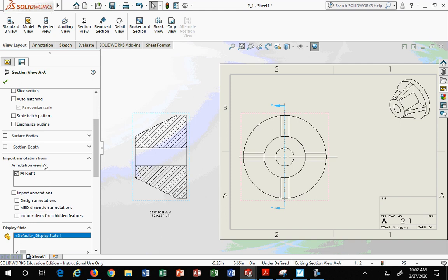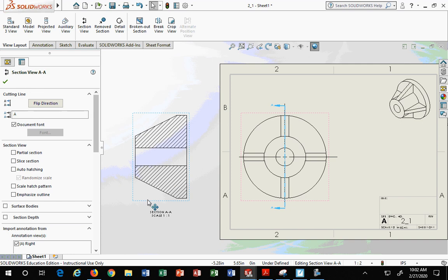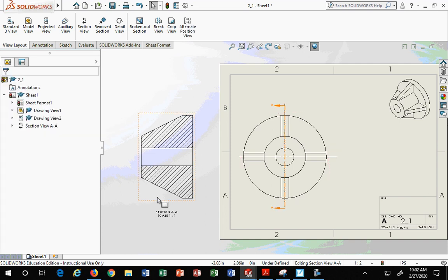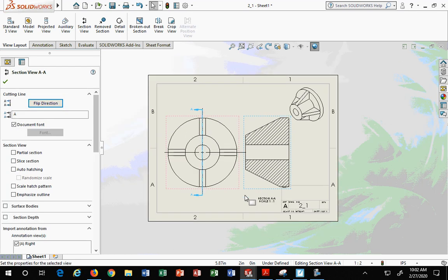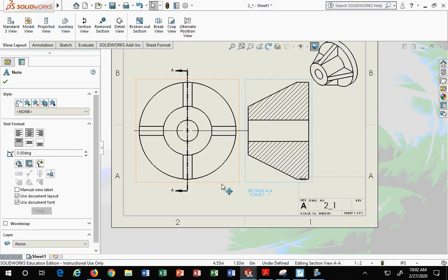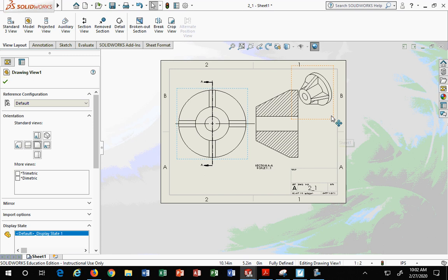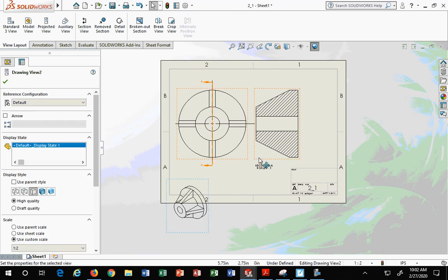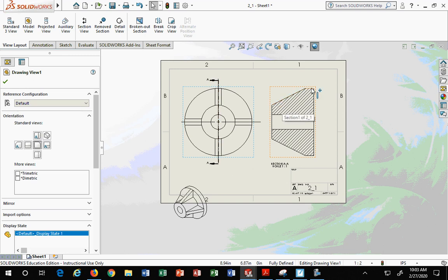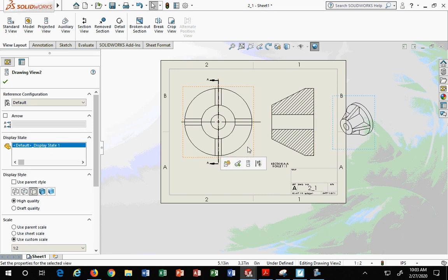Traditionally speaking, for today's conversation, you want to do a basic sectional view. You want to end up with something like this. You're not going to be totally happy with it because you're taught in hand drafting to do what? If you have a rib, what are you supposed to do? I'm going to move that out of the way for a minute. If you have a rib, you don't hatch the rib. But here in CAD, you've got a rib, and it's hatching right through it.